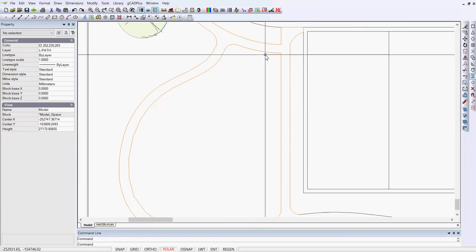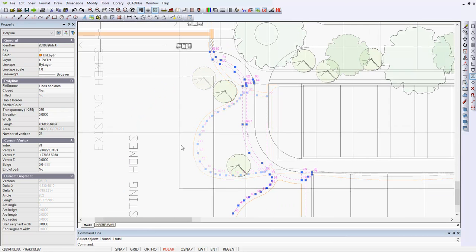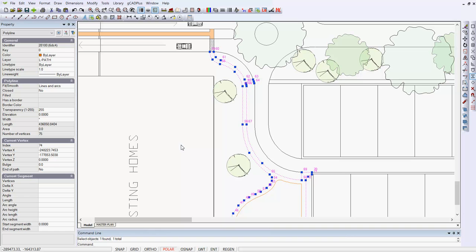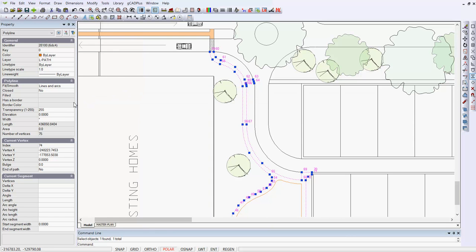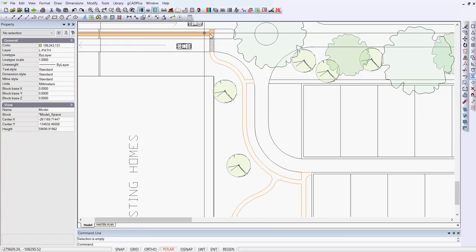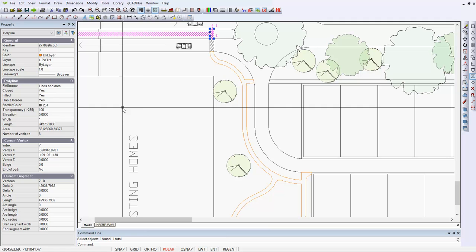And there we are. Now if we wanted to, we could apply a fill. So we've pretty much achieved our aim. We've created a closed polyline over the entire sort of natural pathway through this development, and once that's completed, it's just a matter of setting the properties of the new one, which you'll notice at the moment is not yet closed and not filled, to the properties of the successful one at the top here, which is closed, filled, and has a border.